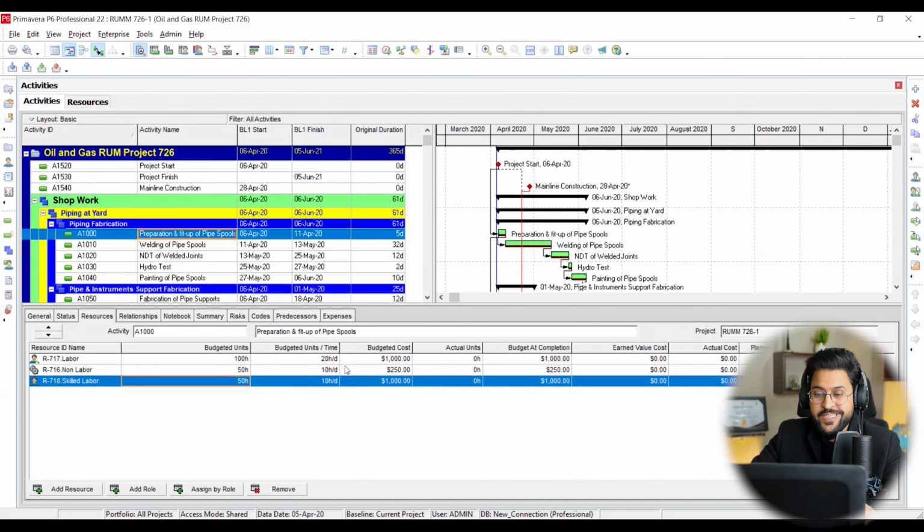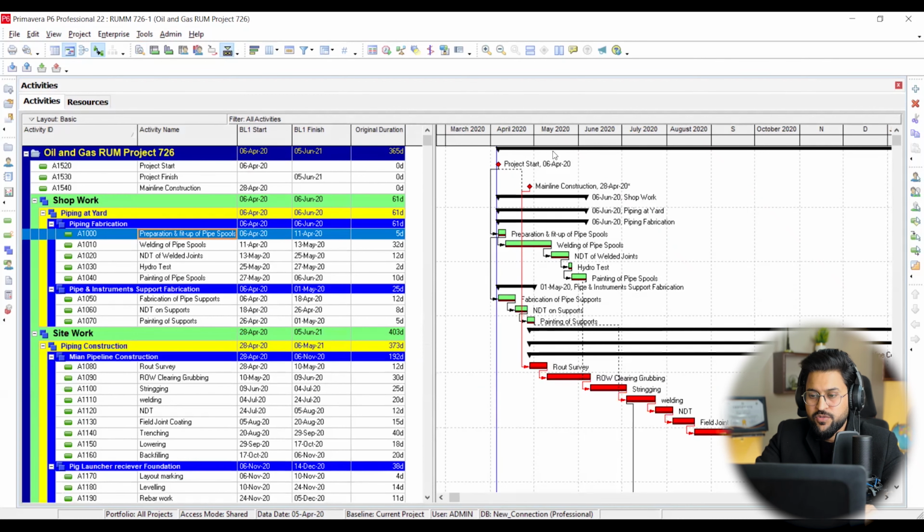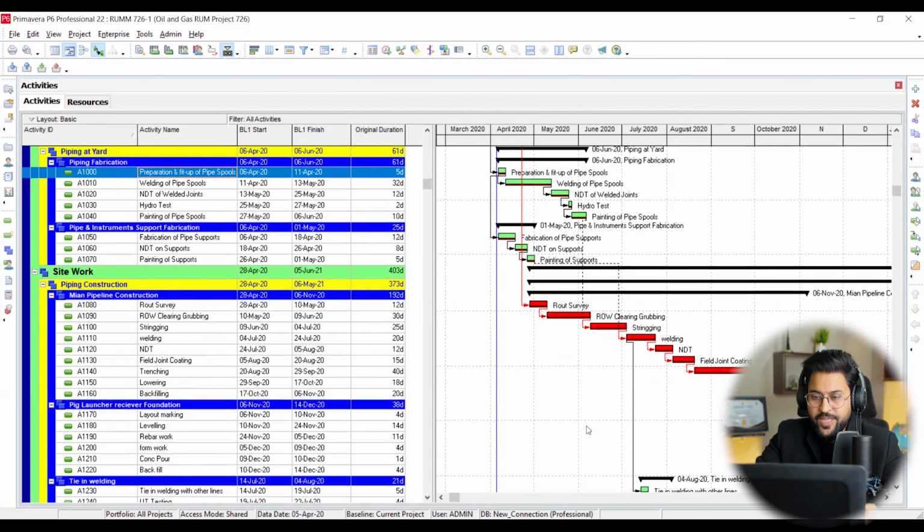This is the most detailed project schedule in which you can see resource deployment and cost allocation being given at the same time. And now we can see this is the most justifiable project schedule in which your cost is attached with total man hours. Your total man hours are attached with your duration, and your duration on the basis of your links is going to define your critical path method. So that is called resource management, cost management, and time management, which go parallel to each other. If I change any one of these factors, it is going to impact the other.